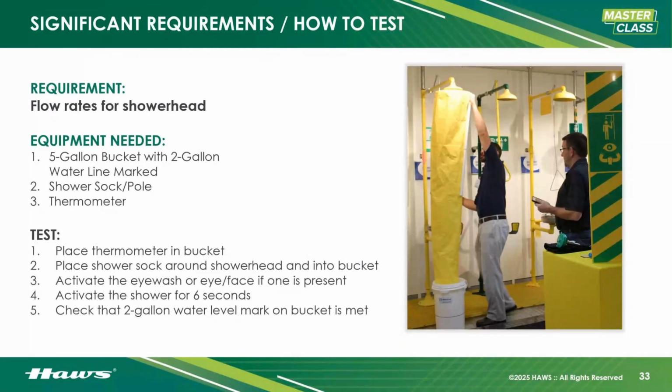Oh, look, I will give you a tip though. I was once on the top of a cooling tower for an energy facility, and we started at like the eighth floor or something. And there's a little string on our thermometer. Tie it to the side of your bucket. I dumped my bucket over the side of the building like he told me to, and my thermometer went 8 stories down. We had to take a long walk down the stairs to go get it, and I was pretty thoroughly embarrassed. So make sure you tie that off.